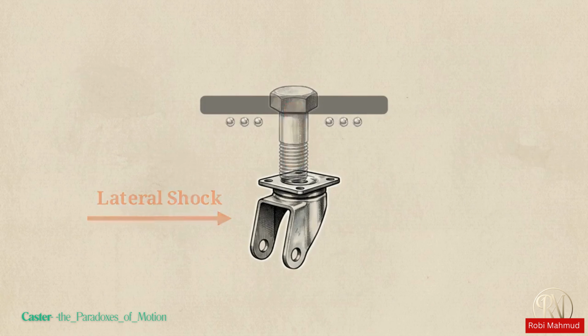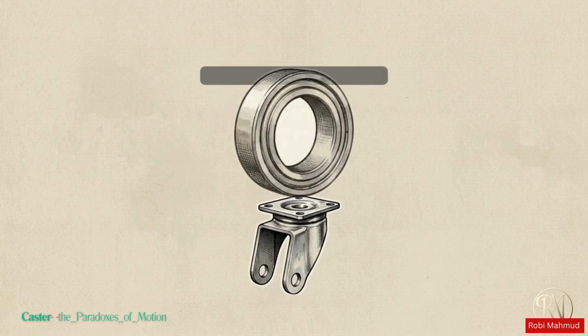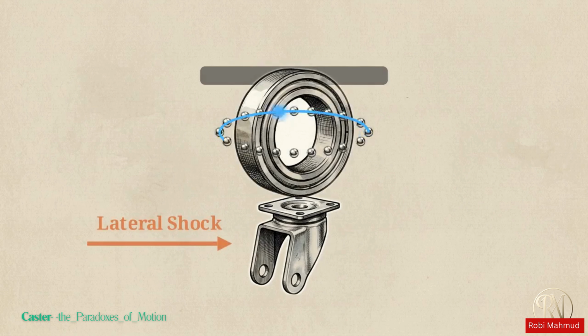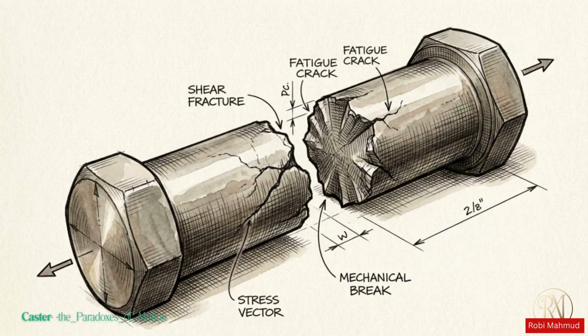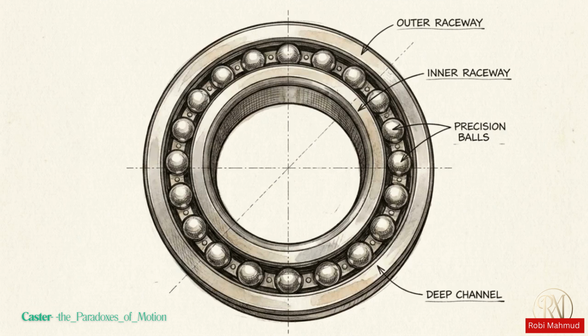The kingpinless solution replaces the bolt with an interlocking raceway of steel ball bearings, safely distributing shock force around the entire diameter. Mechanical strength is not found in the thickness of a single anchor, but in how effectively the design can distribute stress through the entire system.